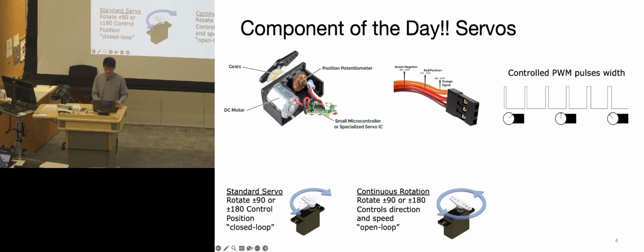And it's a very convenient three-wire interface, one of them power, one of them ground, and the next one is basically a one-pin connection, one-pin control to a certain extent. It's controlled through PWM, pulse width modulation. I'm not sure if you worked with this in previous classes, but you certainly will in the later part of this class.